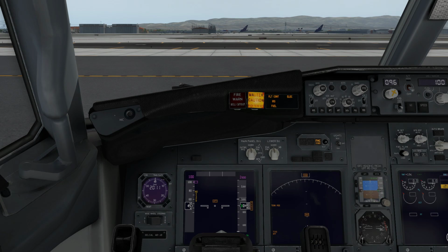You'll notice on our primary flight display, the left little screen on the panel, and our navigation display, the EHSI right-hand screen, they're both basically blanked out. We've got some things there, but those will kick in when our nav is aligned from the IRS above. So you can look up there. There's a way to see the time. We can just wait for those to kick in.